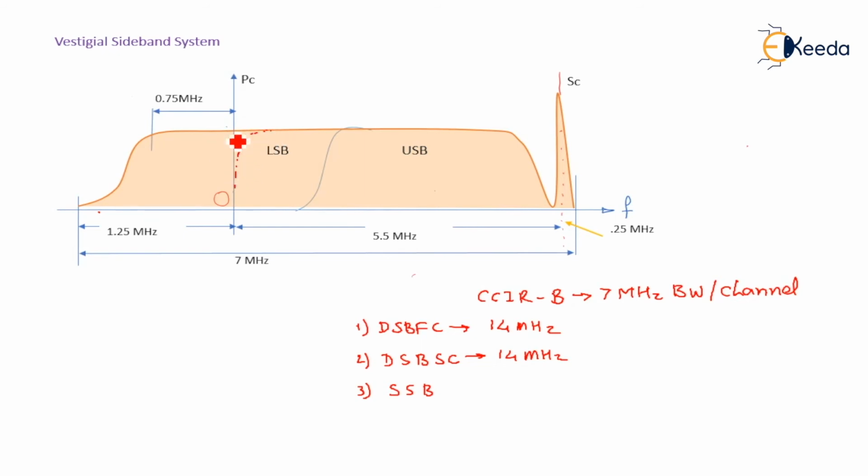Near the picture carrier, this frequency is 0. So near the 0, the lower frequency range is carrying more important information related with the brightness and contrast of the picture. If we provide the attenuation here, I cannot do that, because some amount of the information may get lost.